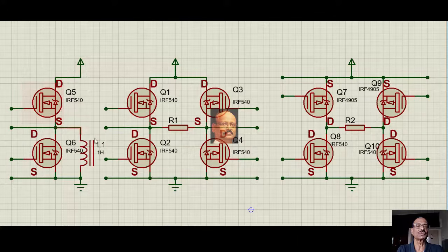In the process, the power flows this way, and the inductor, whatever it charges, comes back this way. So that is how an AC flow takes place here, in a half bridge situation. In a full bridge situation, we have four N-MOSFETs where two MOSFETs have ground reference, that is, the source is ground. Here these two MOSFETs, the upper two MOSFETs, do not have ground reference. So we have to give a drive with respect to source at the gate, that too positive supply.